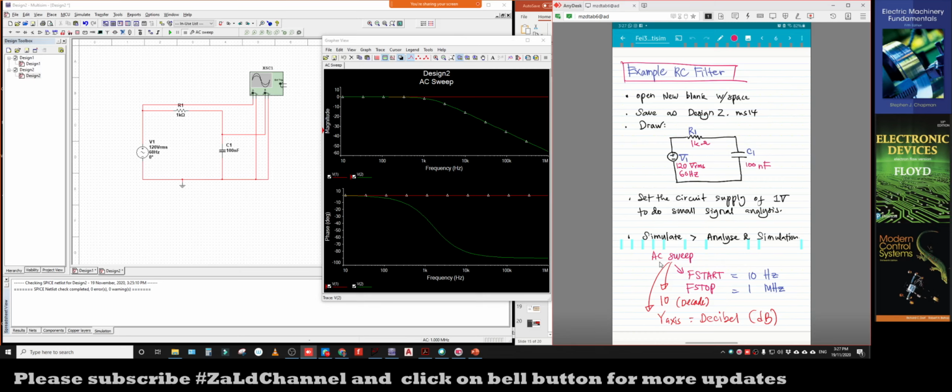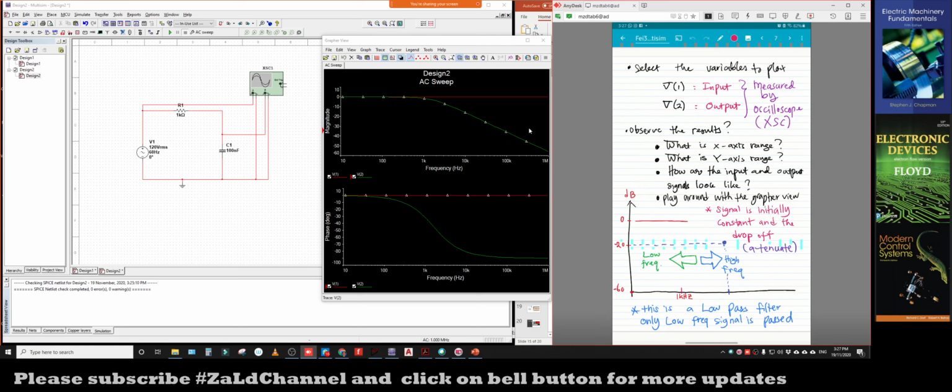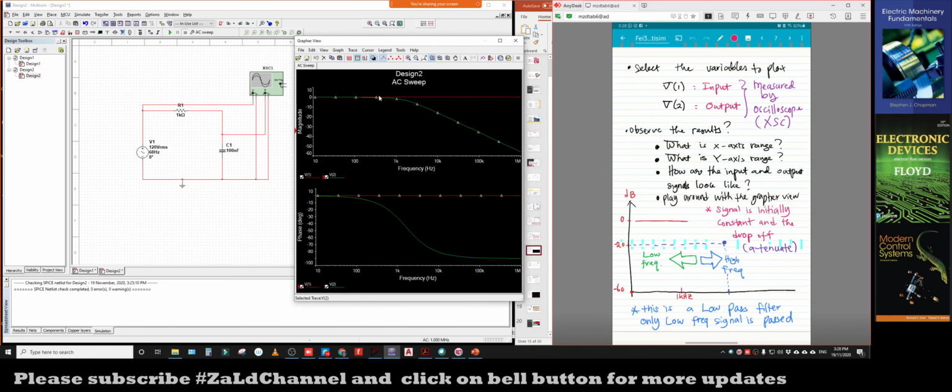This is the AC sweep analysis for an RC circuit. We have the RC circuit here and we do the AC analysis. We specify the frequency, which starts from 10 hertz to 1 megahertz for the X axis, and then we specify all of the simulation in the analysis and simulation tab. Then we select the variables we have to display in the output. For example, the red one is the signal for the input, from this probe, and the green one is the signal for the output, from the other probe. So the red one is the input.